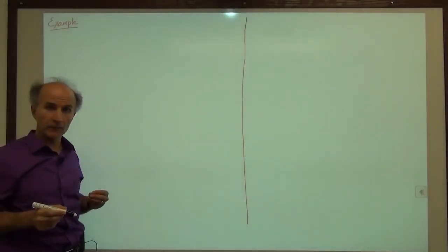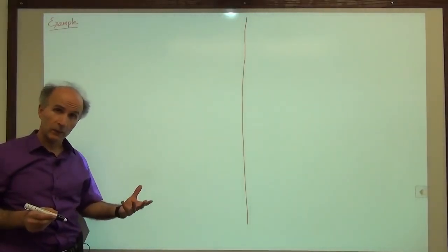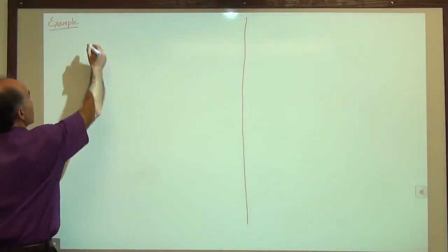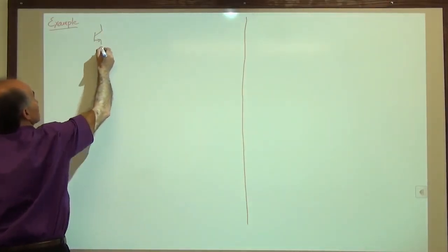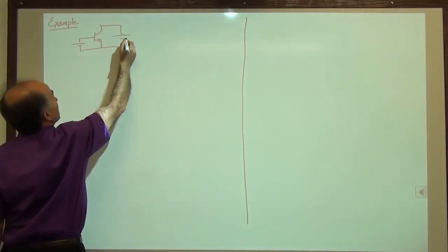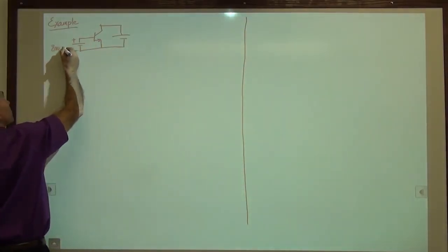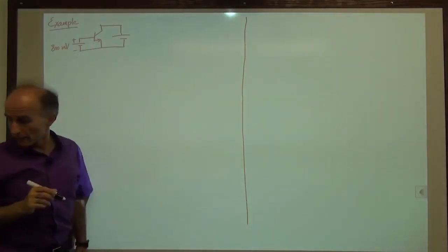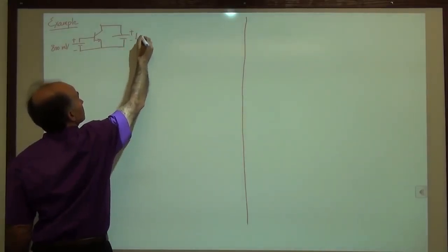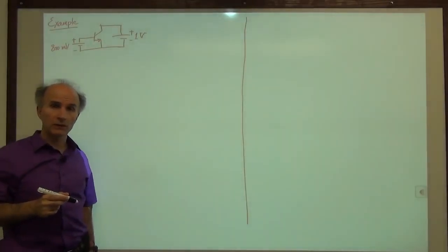We will assume that we have a bipolar transistor and we are biasing it, and we would like to find the small signal model of that transistor. So here's a transistor that we have biased with two batteries. This battery is 800 millivolts, and the other battery I have chosen to be 1 volt. Our objective is to find the small signal model of the device.